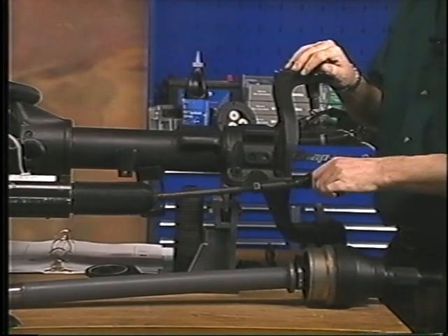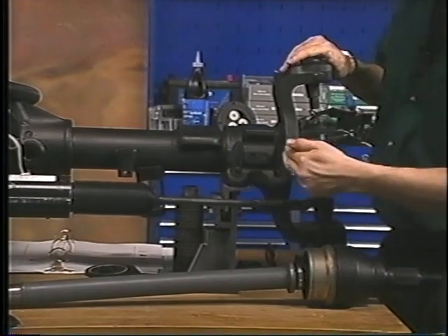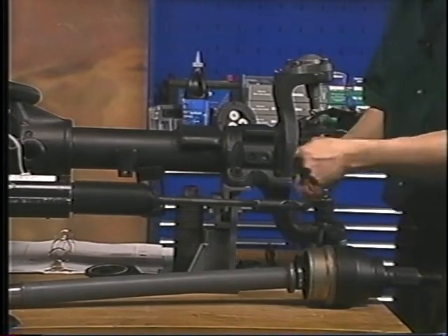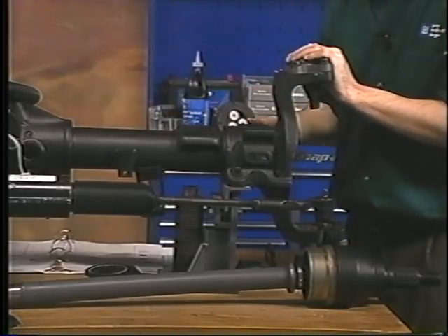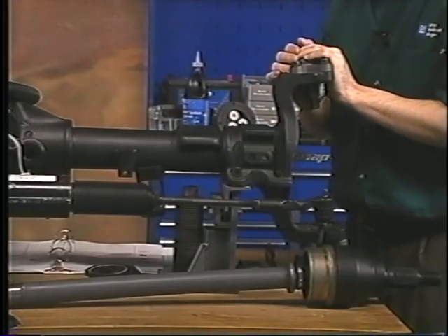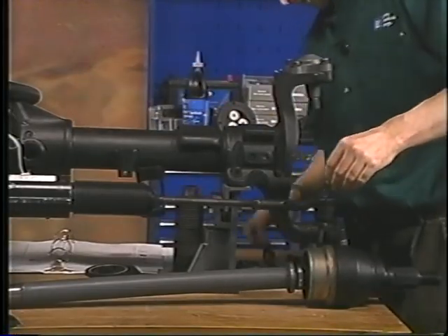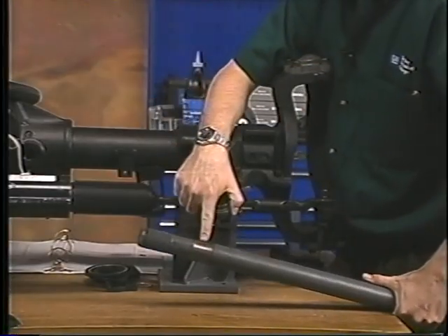Now, we know that we no longer have a conventional wheel bearing, do we? No longer do we have wheel bearing out here in the end. We got that integral wheel bearing out here. So we no longer have our rollers back here, which means we no longer need to supply lubricant down the axle shaft, lubricating the outer bearing. So I'll tell you what, let's put our oil seal right there. Let me grab it. Where's that? Here we go. Look at that. That's where our oil seal rides.